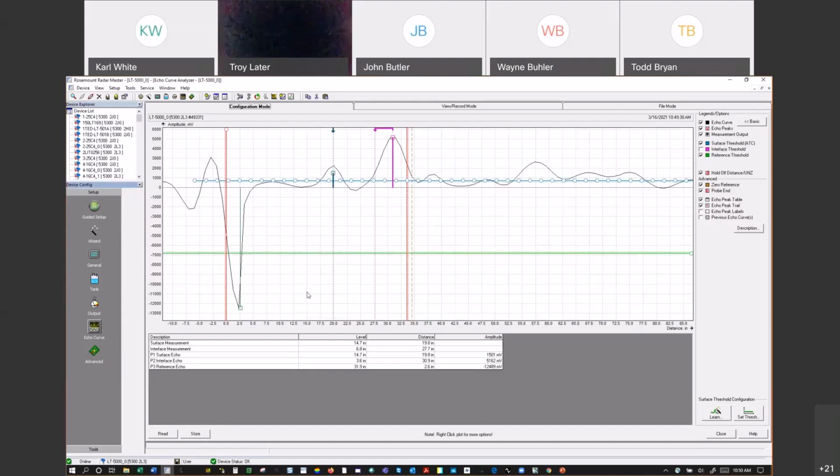Yeah, kind of our rule of thumb is we tell operations to try to stay above 8 inches. As a rule of thumb, we say if you're skimming levels and everything, whenever you get to 12 inches, stop it, right? So this is pretty compelling.